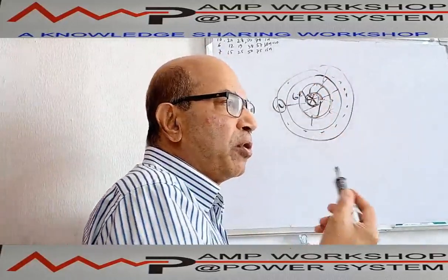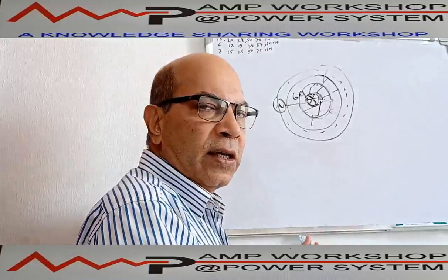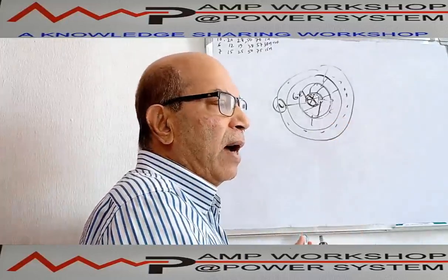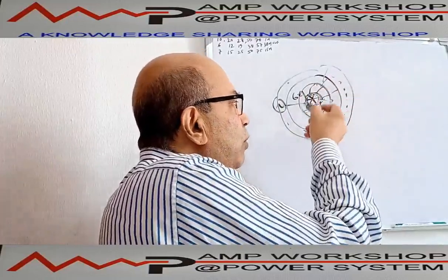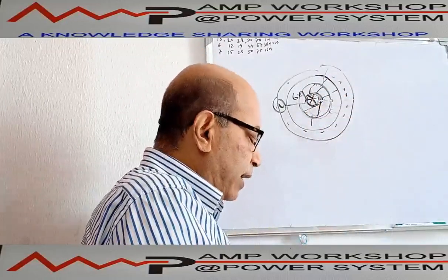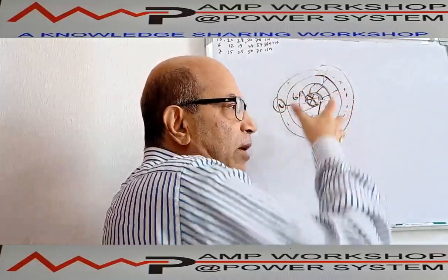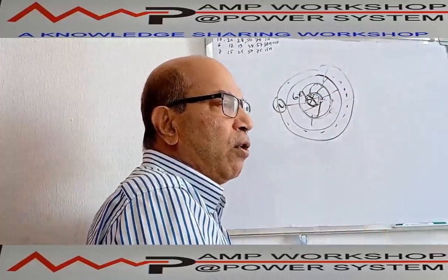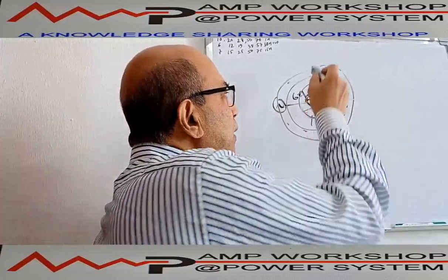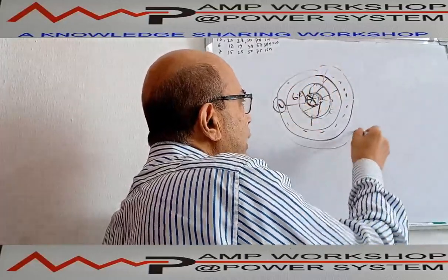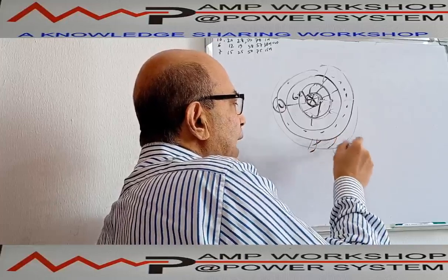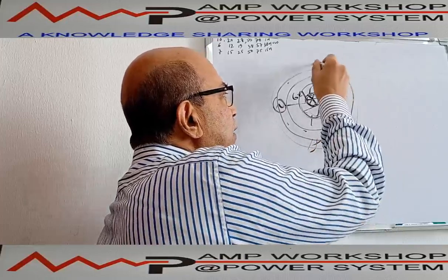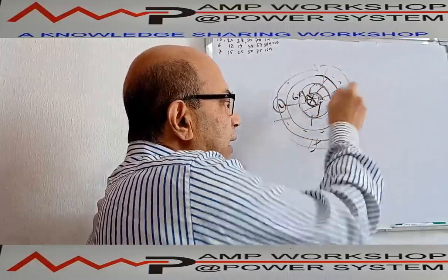It could be aluminum, galvanized steel, stainless steel, normal iron wires, or aluminum wire. So different materials it could be, and this material can get damaged with time. To avoid the damage of these wires due to pollution, contamination, we need another plastic material cover, a non-porous material, so that no gas or liquid can penetrate to this armor. So there will be another layer.